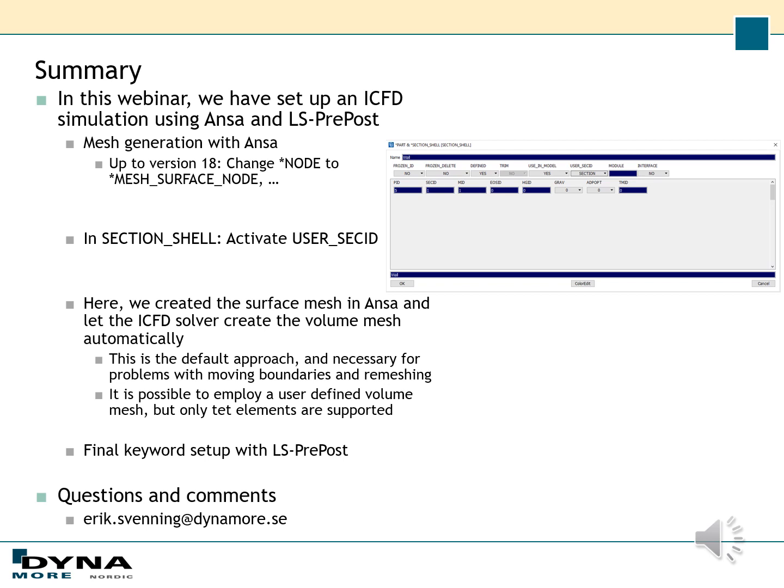And also for the conversion from part to ICFD part to work smoothly, you go to section shell and activate user sec ID.